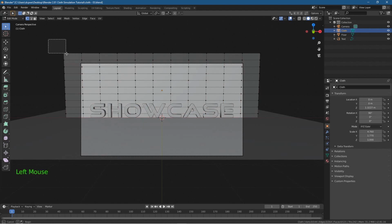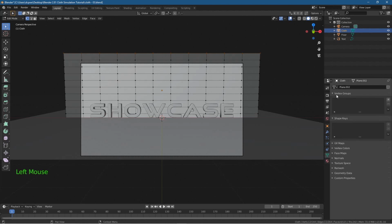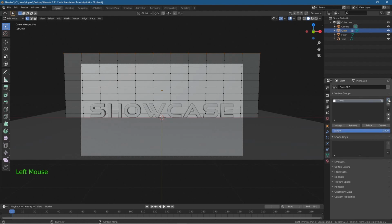So hold down the left mouse button and use the square box selection tool as default, and just select the top edge here, just this top edge right here, all these vertices. And we're going to go to the vertex groups here, and we're going to create a vertex group. Let's click the plus sign and double click where it says group and call this something like top edge. Just type it in, top edge, like this, and then click assign.